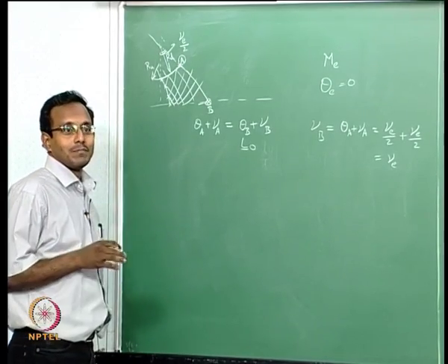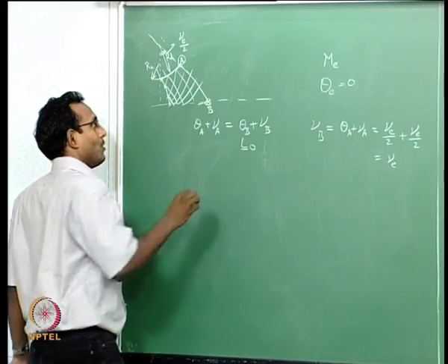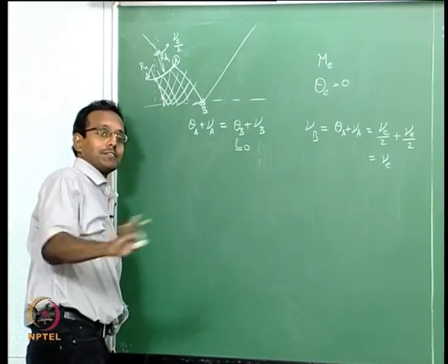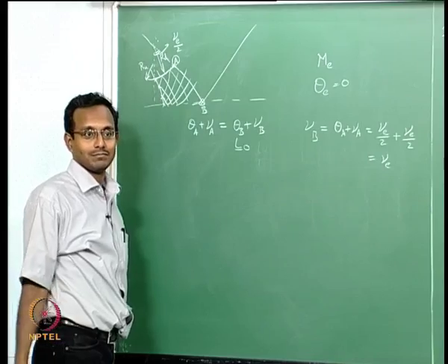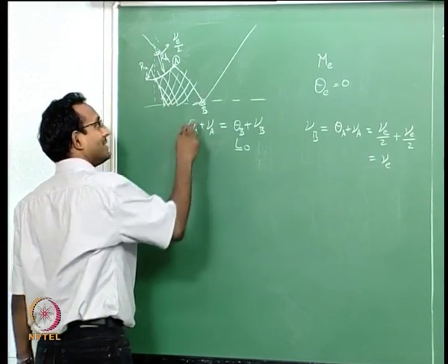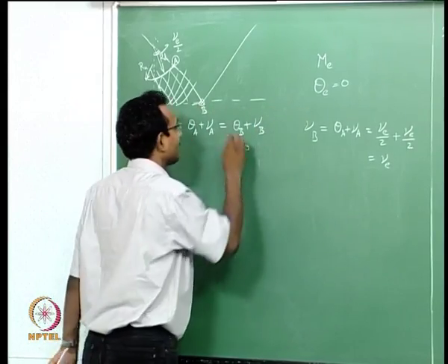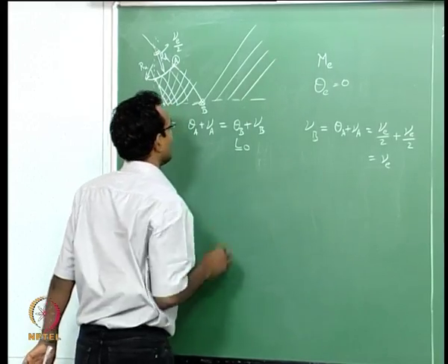Once I get that Mach number, I do not want any expansion or compression to happen. So, after this I want this characteristic to just go straight, no changes. That is what I ideally want. Okay. Once I think about that, remaining things are easy. After that, every characteristic should be parallel. Then I have achieved whatever I wanted.